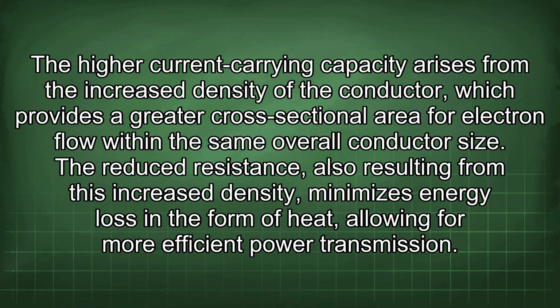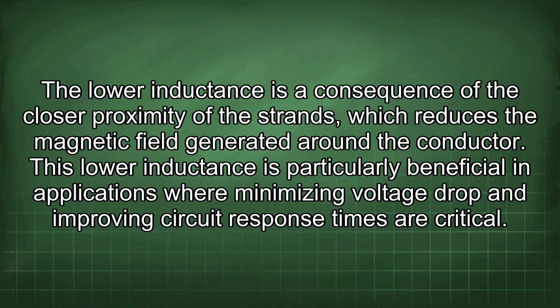The reduced resistance, also resulting from this increased density, minimizes energy loss in the form of heat, allowing for more efficient power transmission. The lower inductance is a consequence of the closer proximity of the strands, which reduces the magnetic field generated around the conductor. This lower inductance is particularly beneficial in applications where minimizing voltage drop and improving circuit response times are critical.